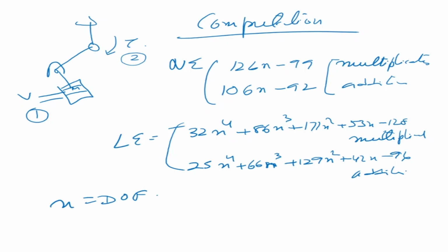So this actually gives us an idea of the number of multiplications and additions required for finding the dynamics, the torques at the joints. And it is not possible to do this in real time. It's very clear from here. It will take some time, not real time. Now, it is known that for n equal to 6, the Newton-Euler is about 100 times more efficient than the Lagrangian-Euler equations.